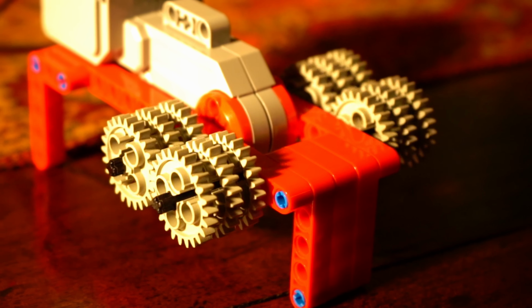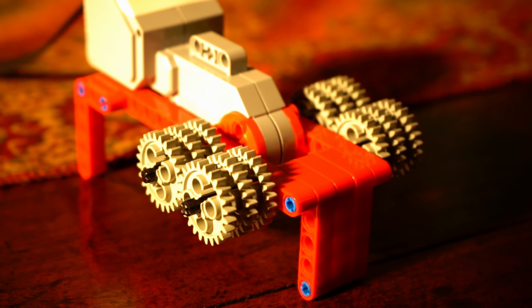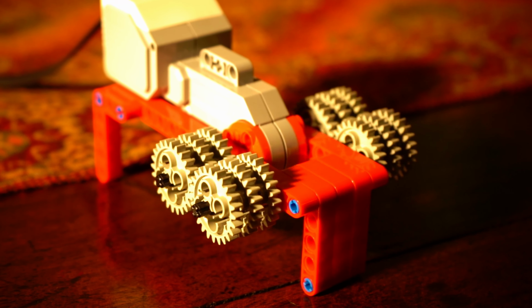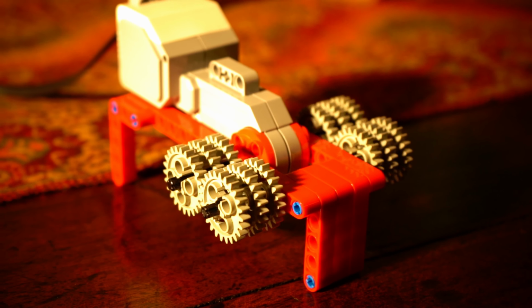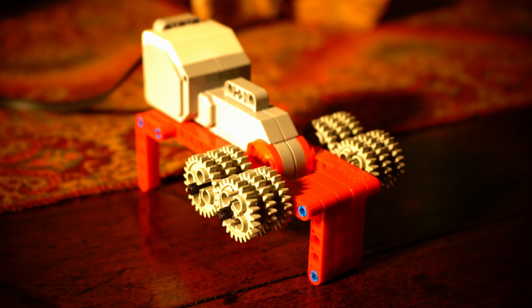The intent of the compound gear is not to modify speed or torque in this case, but rather to more evenly distribute torque across more gear teeth simultaneously. This provides greater strength and stability, but can increase friction substantially.